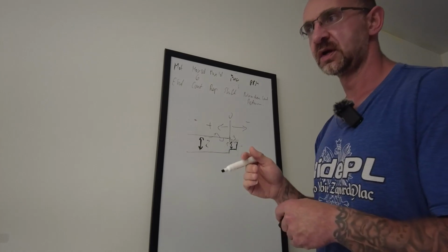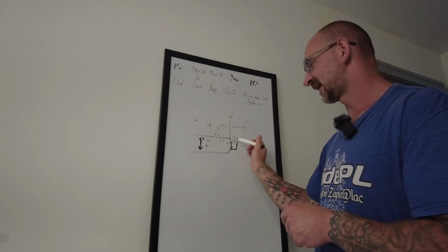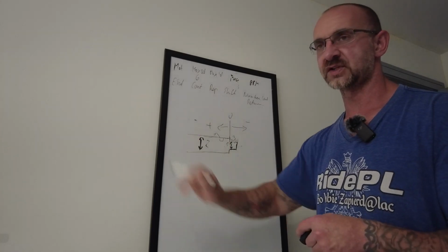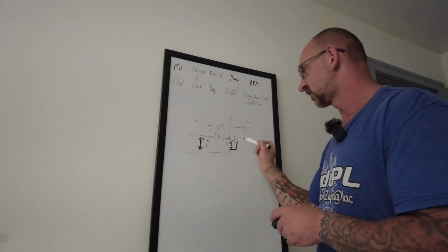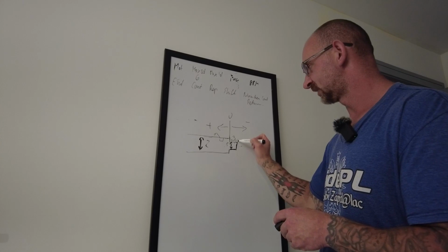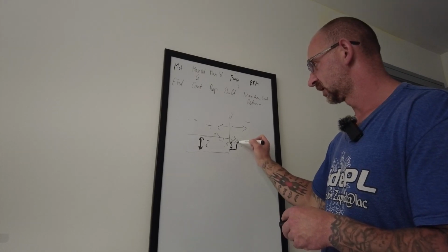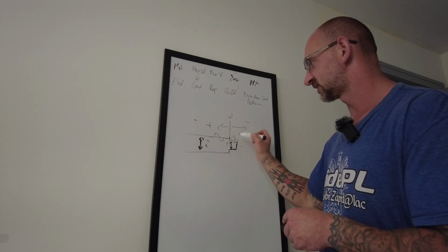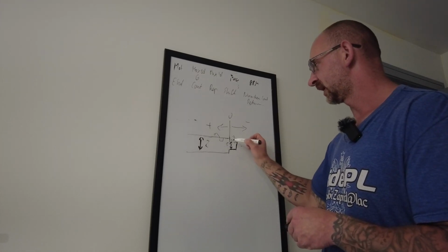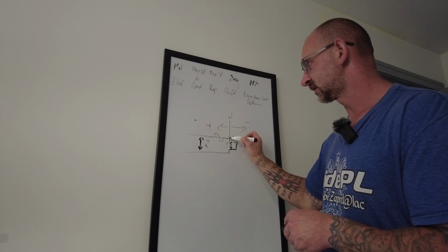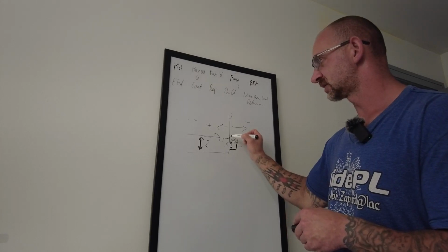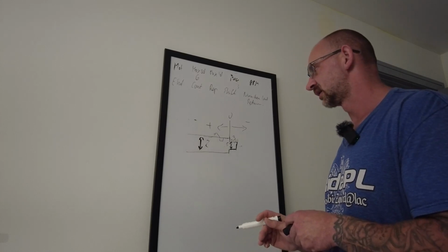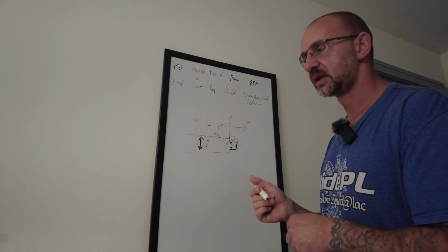You don't have to take that 300 stock to set it 0 and then just add 300 to pretty much all these features that you have, because you can go from minus 300, do a line, your finishing line on a Z is gonna be a 0, and then you start another line and let's say 2 inches, and then you do all your features or whatever you're turning as you normally would.